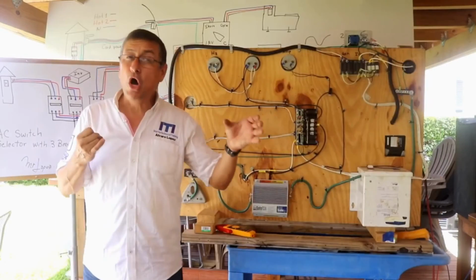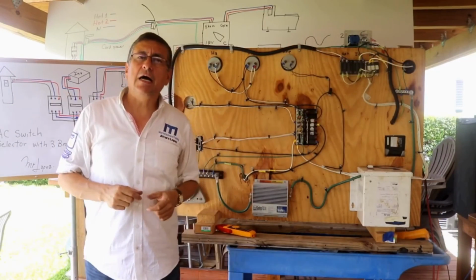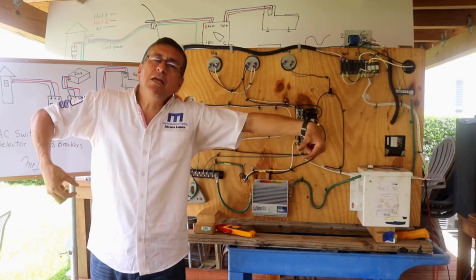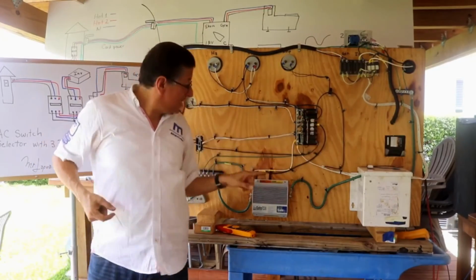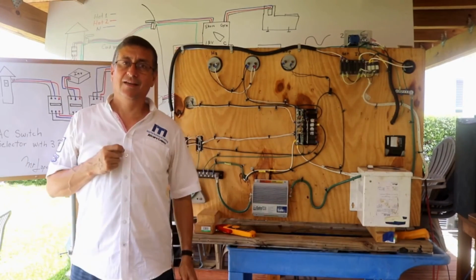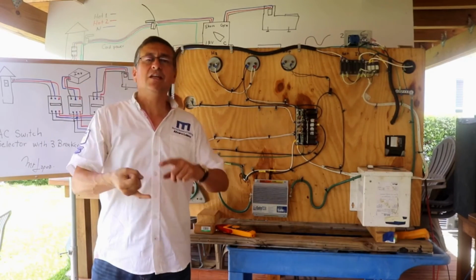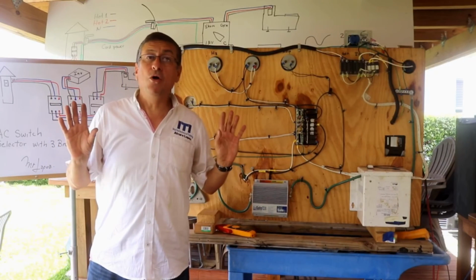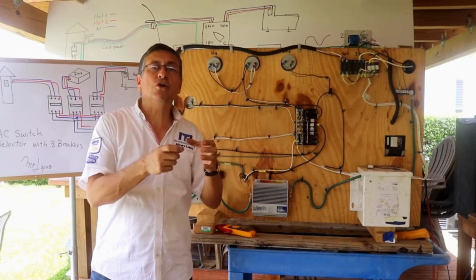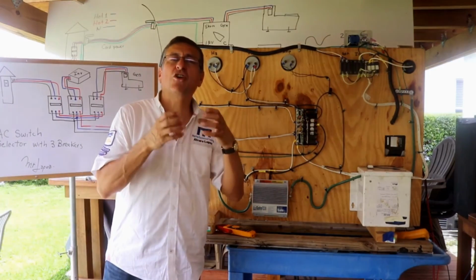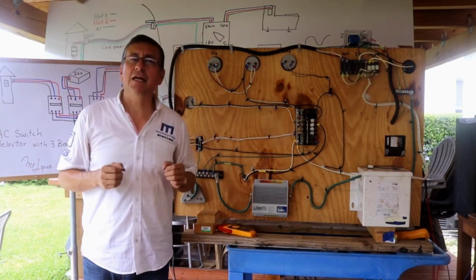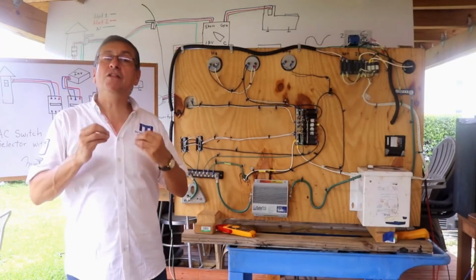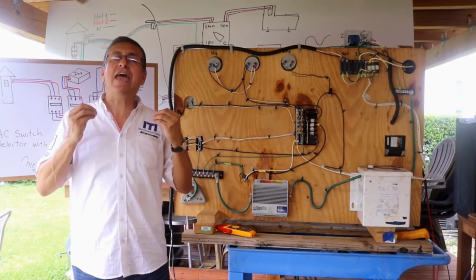You remember? The through holes, the metallic fuel tanks, all the metals inside of the boat shall be connected to the bonding metal. If the bonding metal right now is hot, the corrosion in the fittings, the corrosion on the through holes, the corrosion on the transducer is accelerated. And the boat suddenly sinks because those elements are perforated, because the corrosion is accelerated. This is critical. If you have reverse polarity in a boat, immediately the bonding has power. The bonding has AC power.